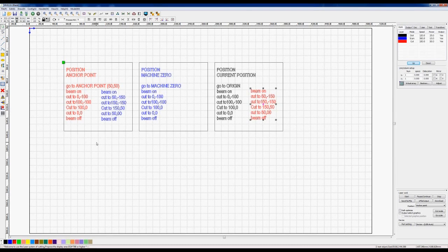So when it runs the program, it makes all the same adjustments that it did when it was using an external origin, but this time, instead of looking outside the program, it looks inside the program for the anchor points that you have set by pressing the origin button. What that means is that you can store this program away on your machine. Weeks, months, 10 programs later, it will still run from exactly the same position because the coordinates are stored inside the program.